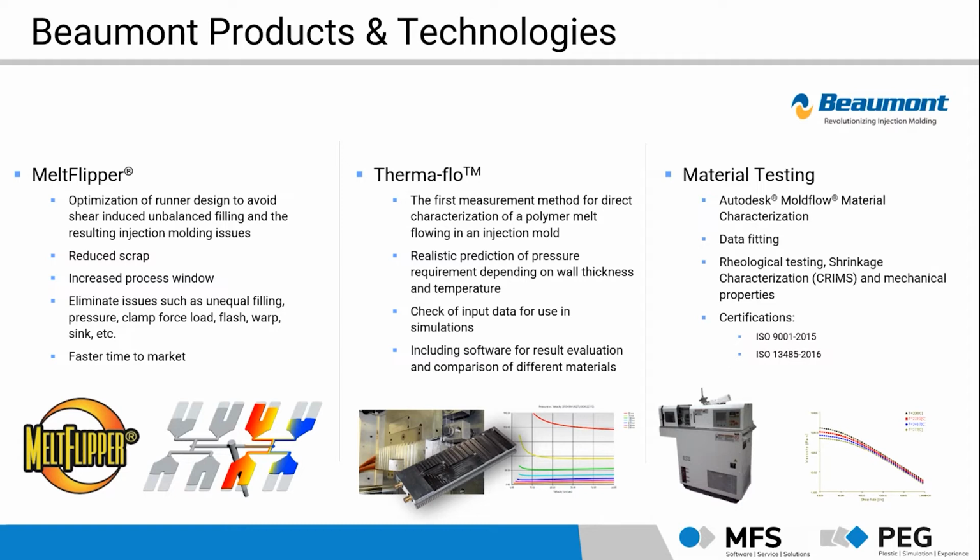This is a measurement which was developed by Beaumont and which takes these typical things like frozen layers, which play a big role in injection molding processes, into account. So this is, let's say, the first measurement method for direct characterization in an injection mold. And the third point here is the official Moldflow material characterization service, which offers material testing and creation of the UDB files for use in the Moldflow software.